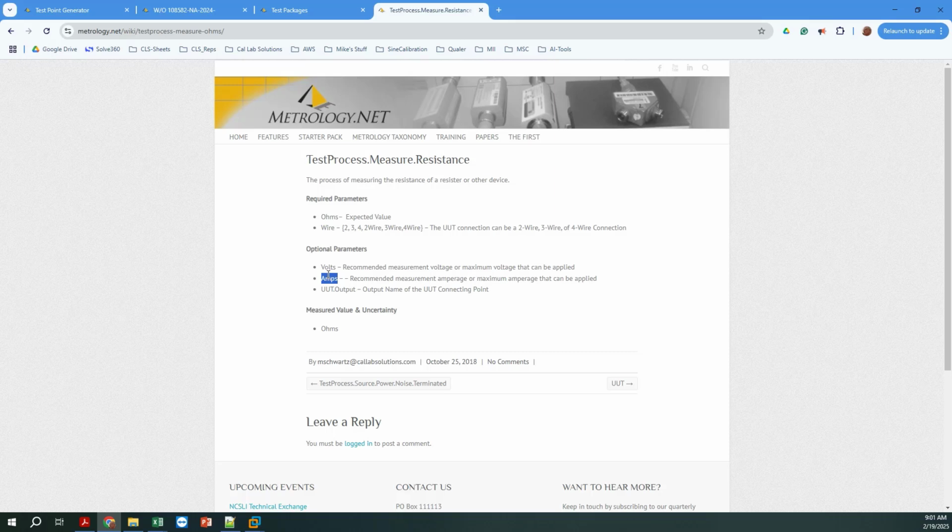It was mostly for me looking at the fixed resistors. Sometimes giving different current into different fixed resistors, they behave differently. So that's why it got put in here this way as a not-to-exceed; it just comes in as recommended current. And I know the 3458 does this. I just can't remember if it was the 8588 or 8508 or both that I've coded this into with the low I.